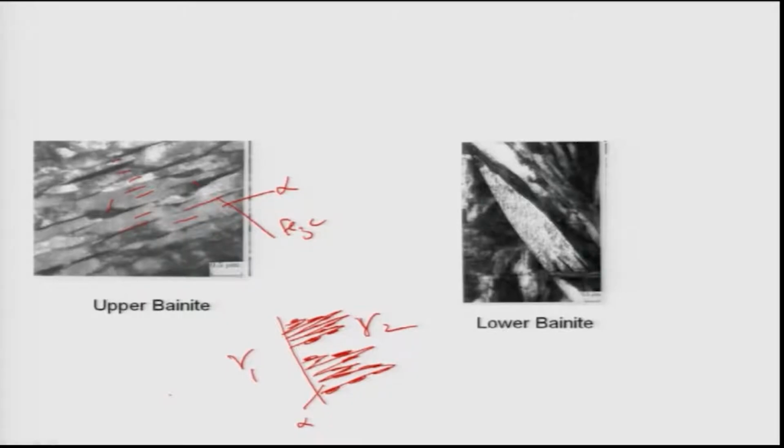So that is what actually happens for the alpha, and this alpha is the same thing as Widmanstatten alpha. They are not like idiomorphic alpha; they actually look like Widmanstatten alpha plates or alpha needles, whichever way you can call them. Many people say needle or plates. Morphologically they look similar. A plate has a third dimension that is quite thick.